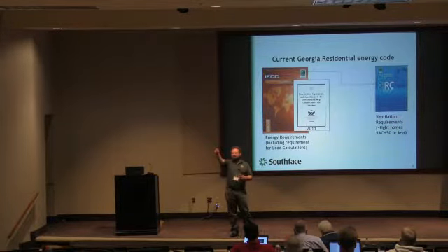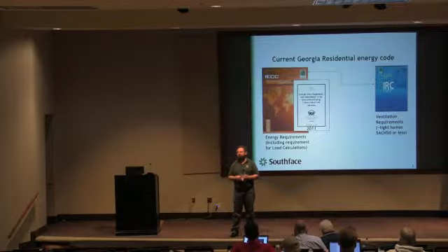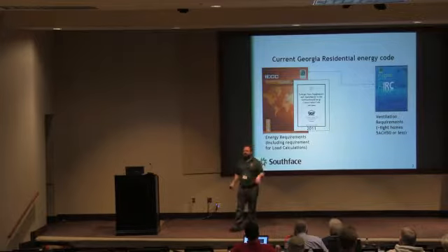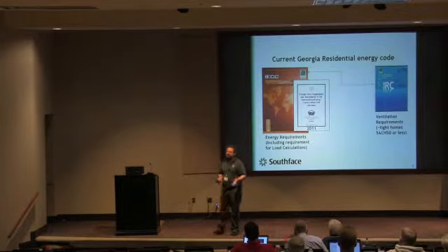I have 2 questions over here. Start right there. The requirement for load calculations, that applies to an existing home as well? It would apply to an existing home when mechanical systems are replaced. Okay. Yes, and I'll tell you, it's probably one of the least enforced things in the code. If you have a 5-ton system, they can come out and swap it for another 5-ton system. Nobody ever does a load calculation.